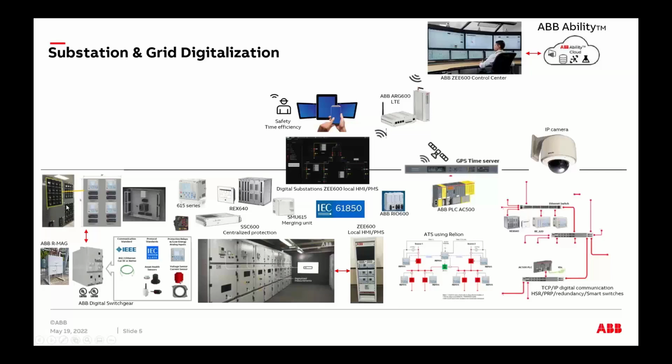When you start thinking about the brownfield on the top here, brownfield projects are actually very, very common, I would say more than greenfield. Maybe 70% of the projects within the US are trying to take an existing panel, I'm giving just an example of a gear, and patch it to take all those devices from analog to digital. For example, maybe EM relays to digital relays, maybe analog meters to digital meters.